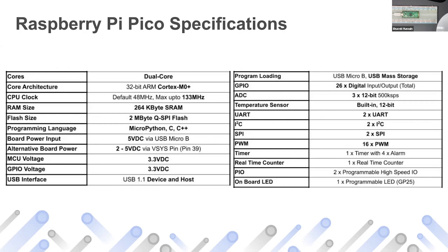And of course, you don't need any special power. You can see in the video, I've just connected a micro USB cable. It's connected to my computer and gets its power from there, right? USB operates at 5 volts, and then there are voltage regulators on board which convert the 5 volts to 3.3 volts, and 3.3 volts has pretty much become the standard for many circuits today.